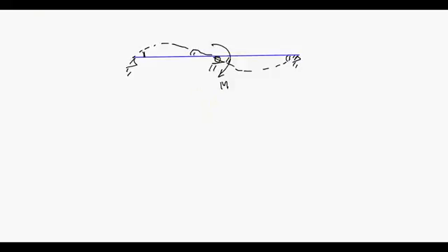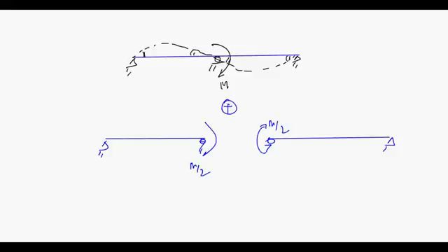Now the way I solved it is, this is your same beam. What you can do is split this beam into two beams. You can assume a pin joint here, roller here, and pin joint here, and you can distribute M by 2 and M by 2. With this M by 2, can you calculate the value of theta? Of course you can. Suppose this is L and this is also L. So this is ML upon 3EI, so it is M by 2 L upon 3EI. What is this value? It is ML upon 6EI.